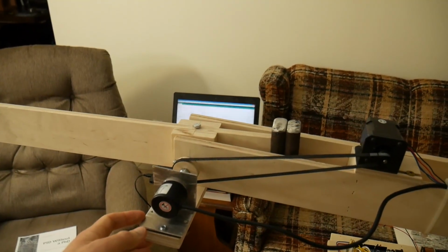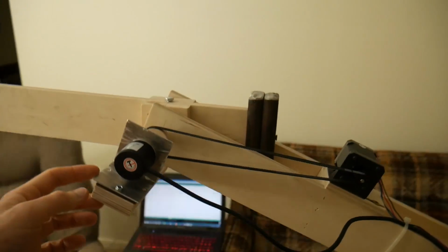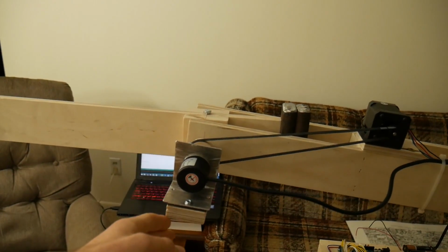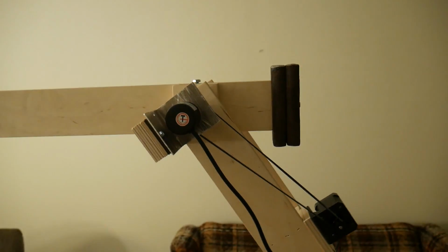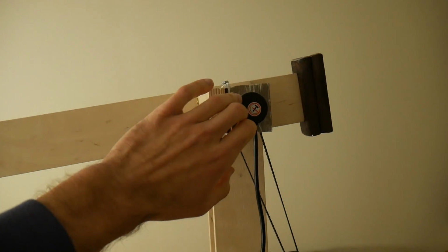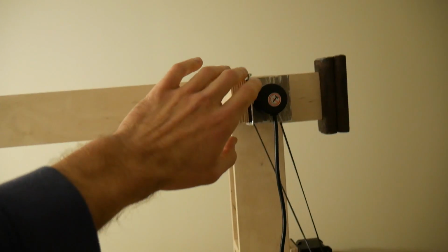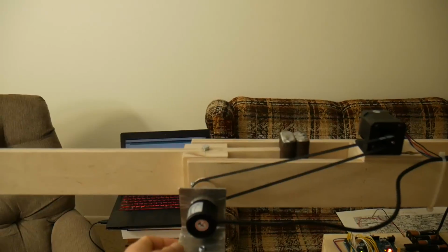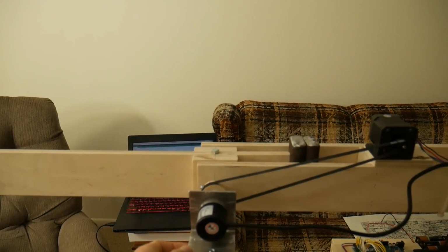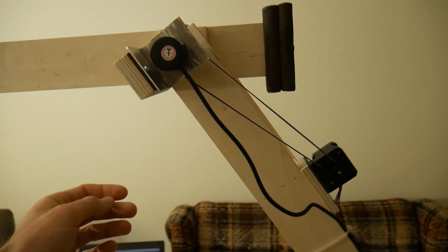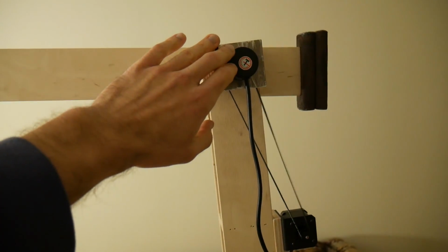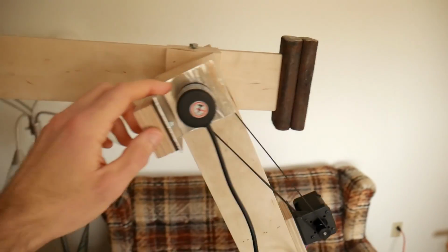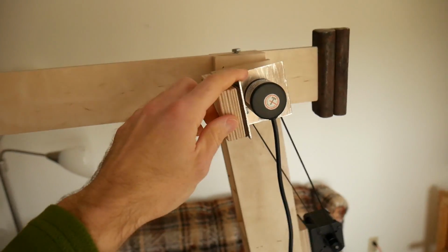By adding in the I and D components of the PID and then adjusting their gains, you can get much better overall performance. Add in too much though, and it'll cause your performance to go right back down. I ultimately settled on some pretty good PID settings, but it didn't seem that necessary overall because in practice I'd be using this fairly slowly, and I haven't really had an issue in those cases. And it does cause a bit of a settling problem, which I was having difficulty with on this machine.